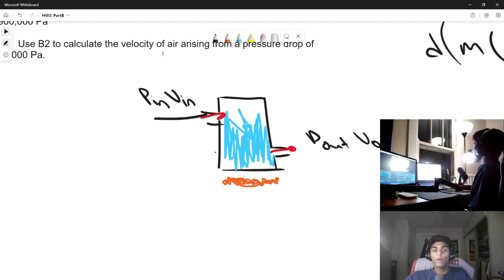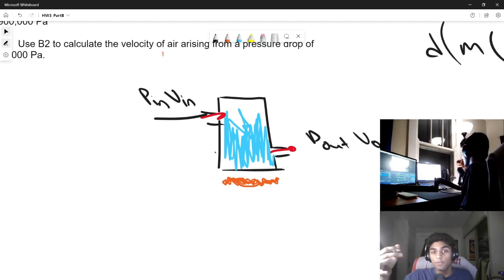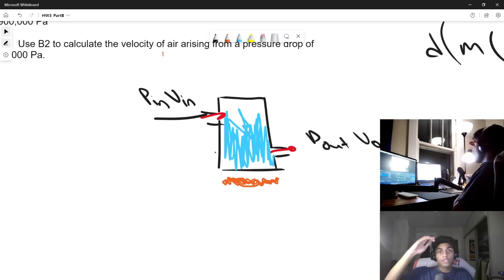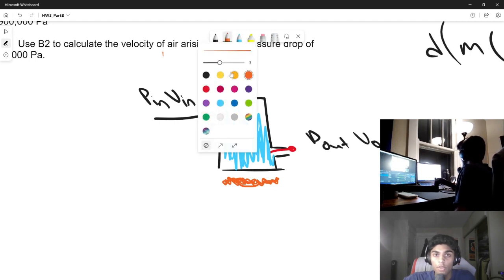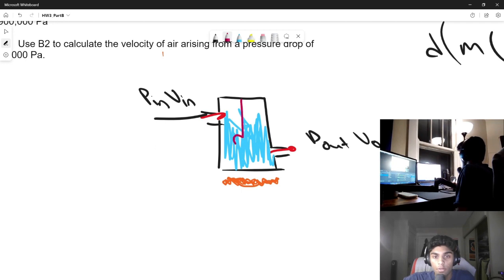However, there are other ways we can apply work to a system. Say if this was a system with gas in it, we could put an airtight piston on the top, and we could compress the gas, and that would be considered doing work to the system. Over here, since this is flow in, flow out, we are dealing with a liquid of some sort. So we can add maybe a stirrer to it. And this stirrer is going to provide us another source of work known as the non-flow work.